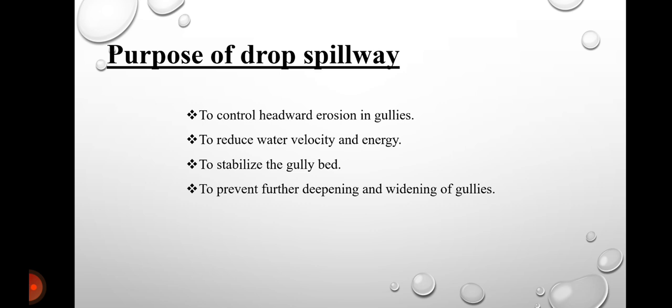Foundations and side walls provide stability and prevent the undermining. So now the advantages of the drop spillway are: provides effective long-term gully control, suitable for areas with considerable elevation differences, protects the gully bed from the erosion, safely disposes of runoff, reduces the risk of the gully expansion.